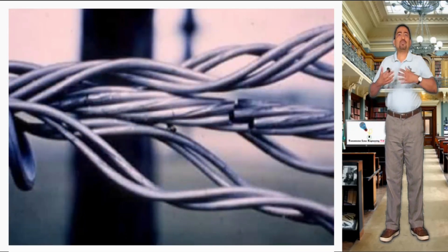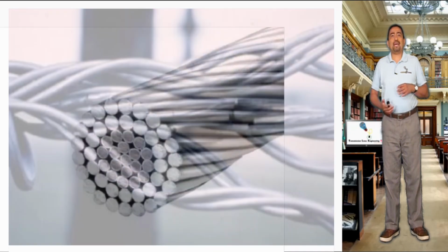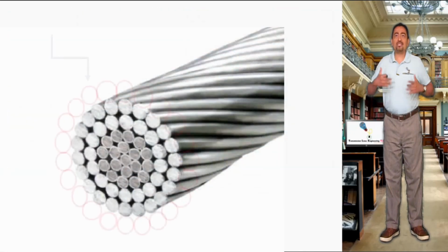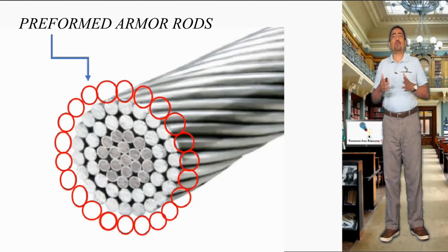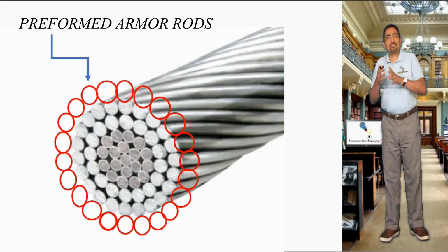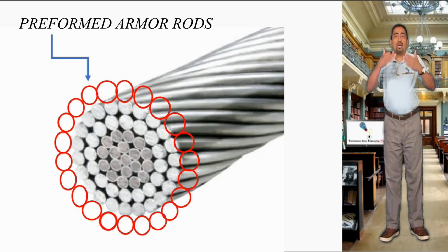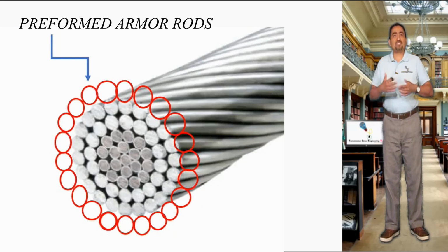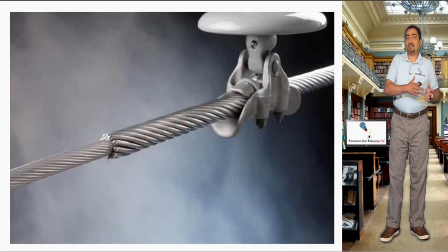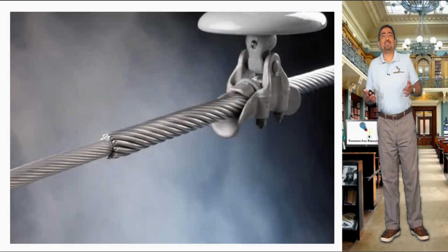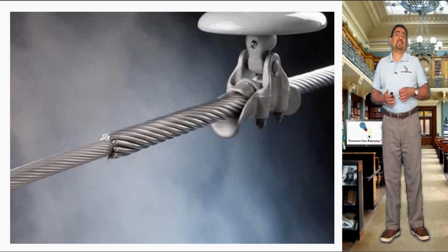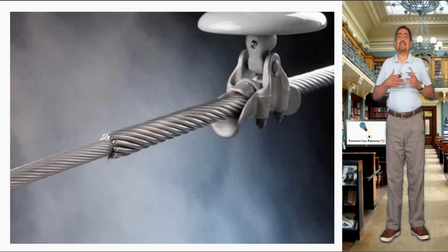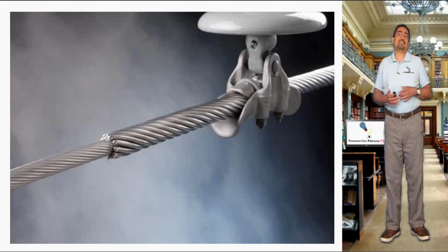So, in order to eliminate this problem, Tom Patterson developed a system of additional stranded wires around the main conductor in the tangent clamps, and in this way the additional stranding will be the one that suffers the fatigue damage and not the main conductor. The only thing necessary is a bigger tangent clamp, and of course replacing the damaged additional strandings.